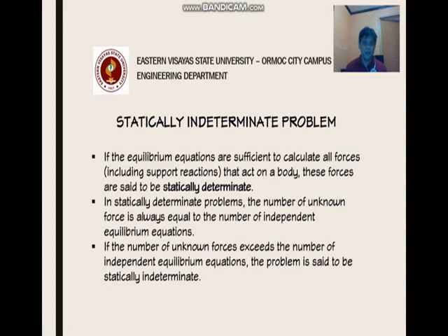So you solve the problem by using summation of forces in the x direction, forces along the y direction, and if those are not enough, then you make use of summation of moments. Okay, so the largest number of unknowns usually is two unknowns.